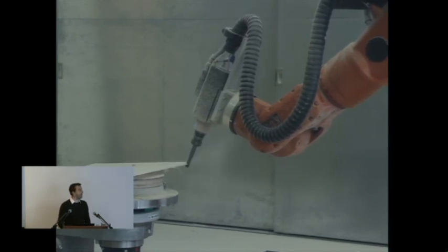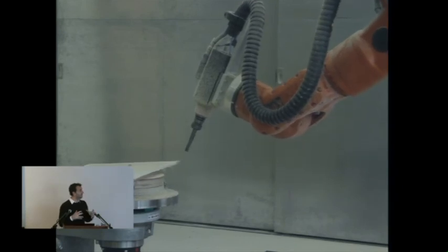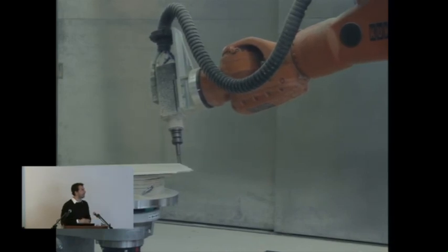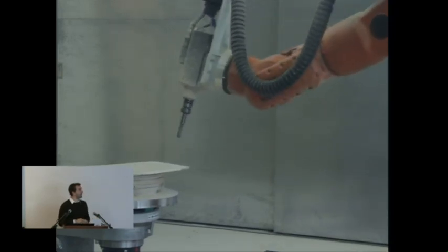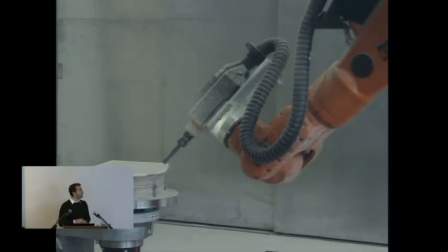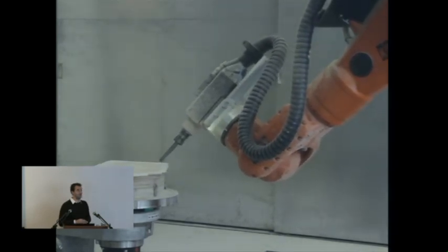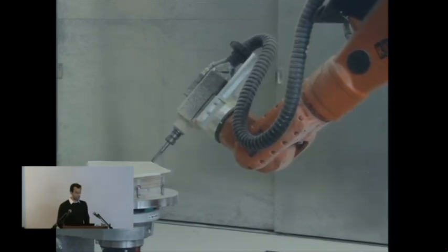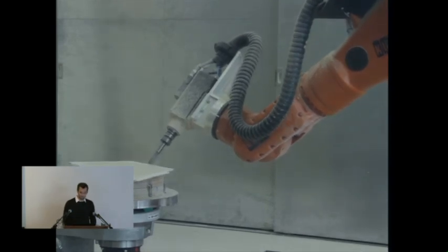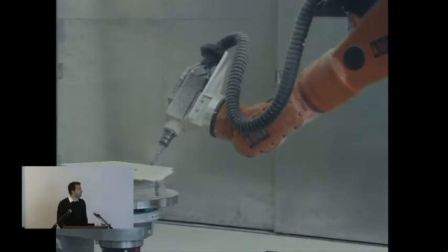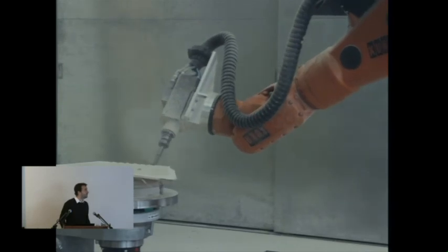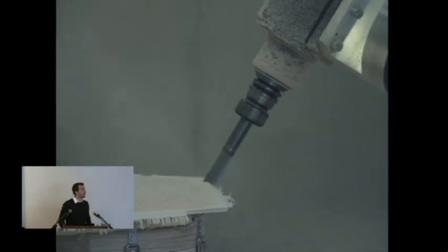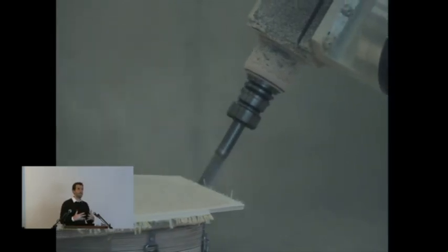So here you can nicely see how the plates are produced. They are mounted on this robotically controlled turntable. Then they are trimmed. That has already happened before the video started. And then the robot cuts the finger joints, as you can see here now, in one go. So it's a relatively fast process. The production of one plate takes about 3 to 4 minutes. And the precision is about 1/10 of a millimeter, because it's really the tool that defines the precision of the joint.